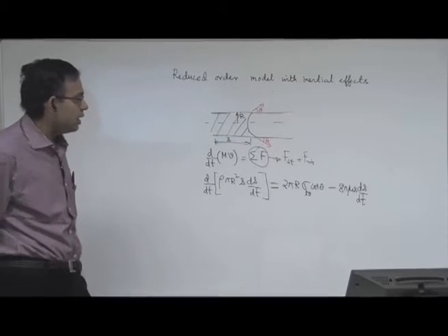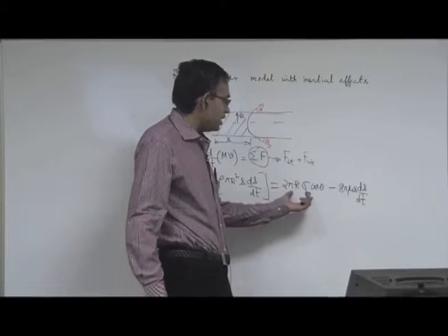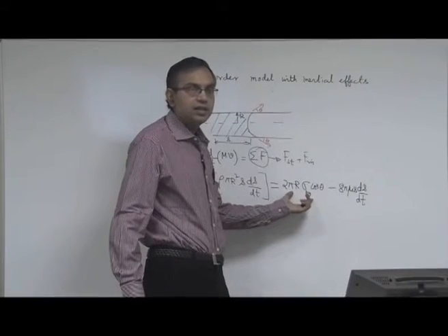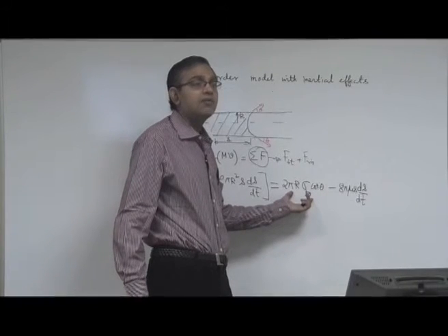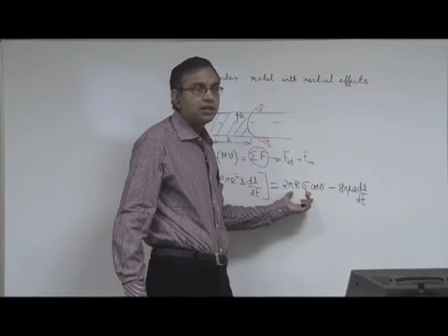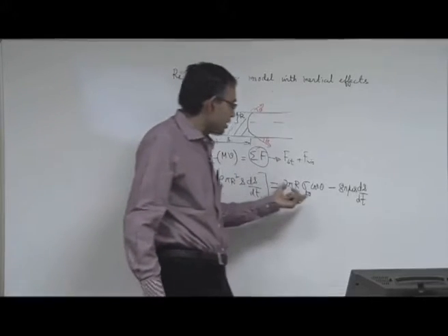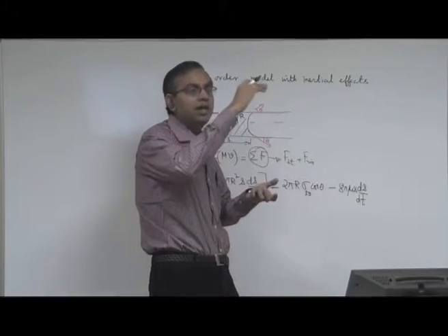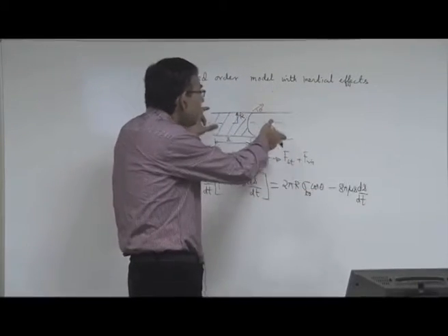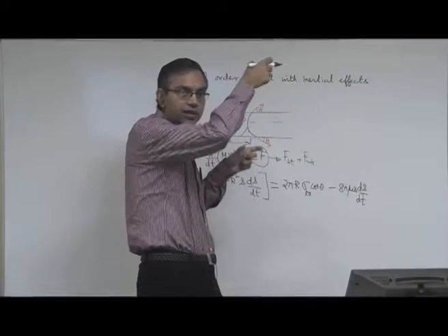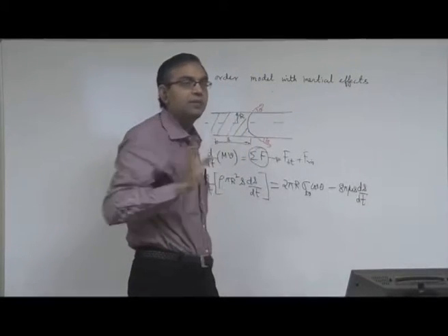Now, a very interesting thing is that if you write this in terms of the static height h, then that may give you an illusion that as if gravity effect is considered, because then they will consider rho g and all this, but that is not true, because the static height is just like a parameter which can be expressed in terms of the contact angle. If this could have been dipped vertically in a fluid, then the amount of rise or fall in the fluid due to surface tension is characterized by that static height.